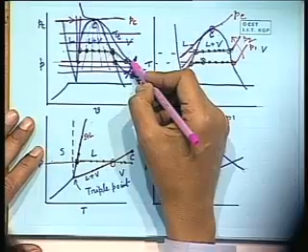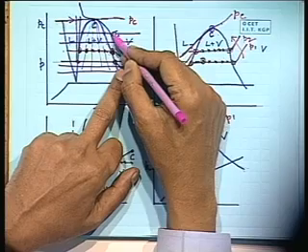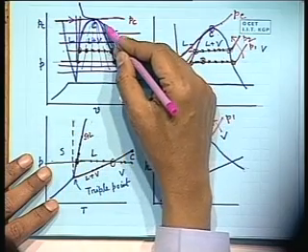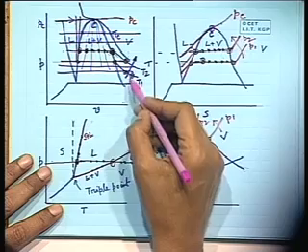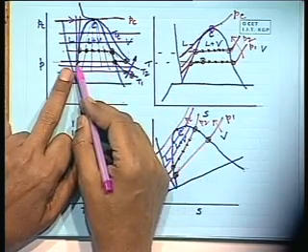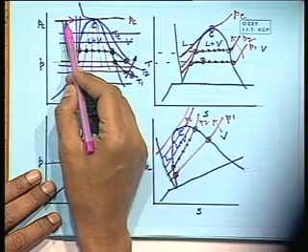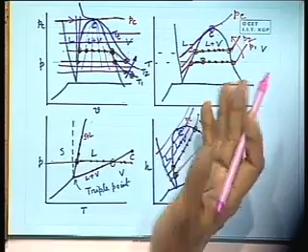For example, at the same isotherm, if you go on compressing the vapor, the specific volume is decreasing and it continuously goes on decreasing. But here, at the same temperature, there is a drastic change in specific volume. There is a discontinuity while the temperature remains the same. You understand? That means we can define two distinct phases below the critical point, but at and beyond the critical point there is no distinction between the two phases. Absolutely no distinction. One phase automatically transfers to the other phase, the books write, but there is no such phase.